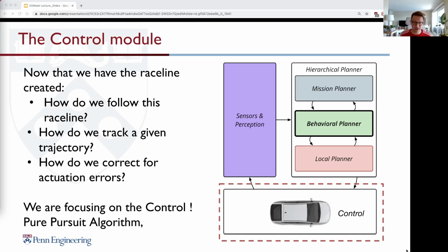And what we are doing here is using a so-called controller. I think everybody heard of that from their studies, control theory. We're trying to track or control the path, and that means for us, we are controlling the steering angle. So what our controller is getting as an input is an error, a distance error for example to the race line or to the next point, and the output is the next steering angle.